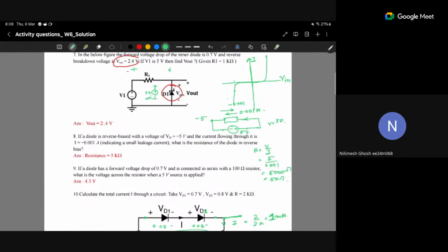Let's say in this circuit itself, we have an external resistance here. Obviously, we regulate this voltage with a Zener diode because we want to use it for a load, right? See, one statement to always remember: the current in a circuit totally depends upon what load you are using. The current will be decided by the load. This RL will decide what current will flow.